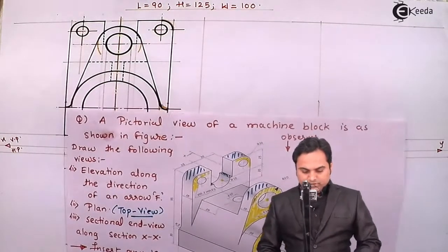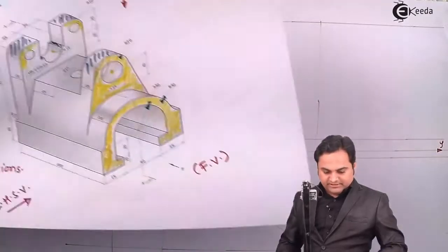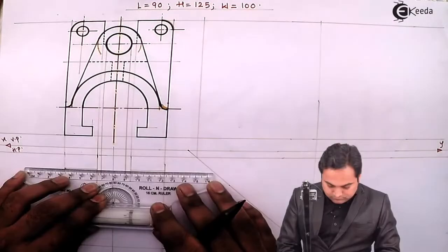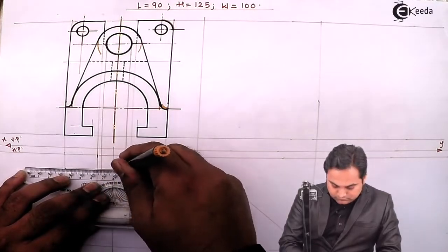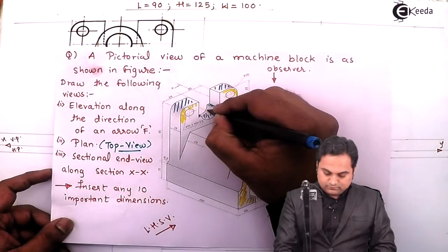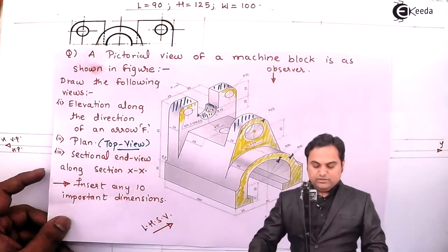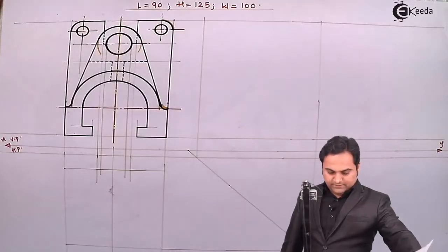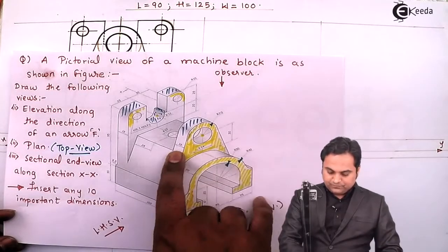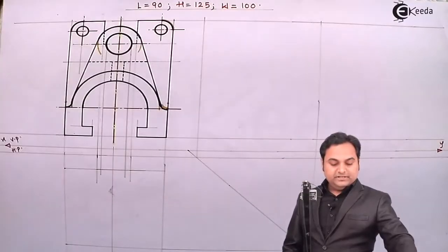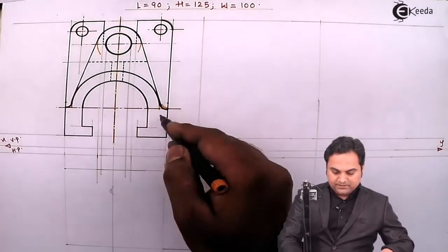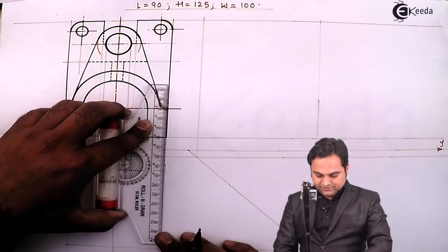When looking from the top, I've projected these two rectangles having the same width as the plate, that is 15 mm. Next, whatever remains is this semicircle, which will look like a rectangle from the top. After that, another rectangle will be visible, corresponding to this portion having width 15. So I project that portion from the front view, where it is in contact with this semicircular part, that is the line which is a tangent.